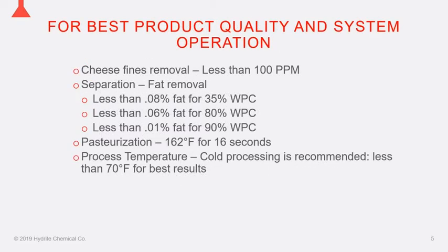So in operating membrane systems, what's really critical and very important to those machines is the quality of the feed and the way that the systems are operated. To get the best optimal performance out of the system, we're looking to ensure that we have the fines removed, knowing we discussed last week the tight tolerances and the mesh inside these elements.